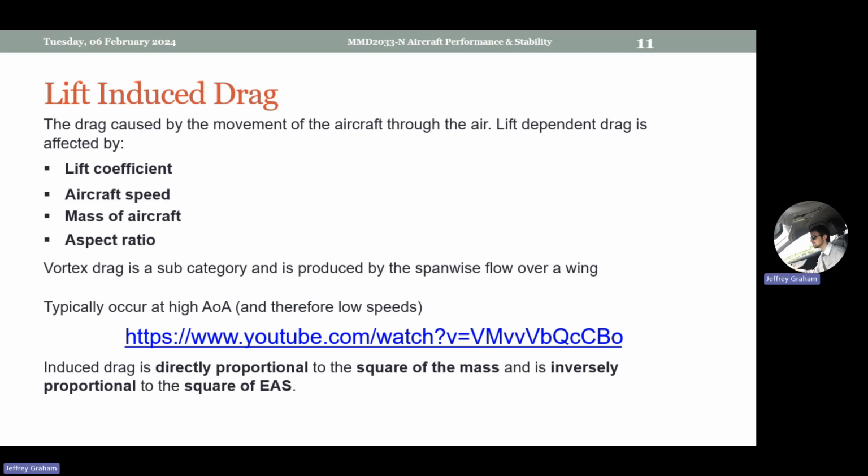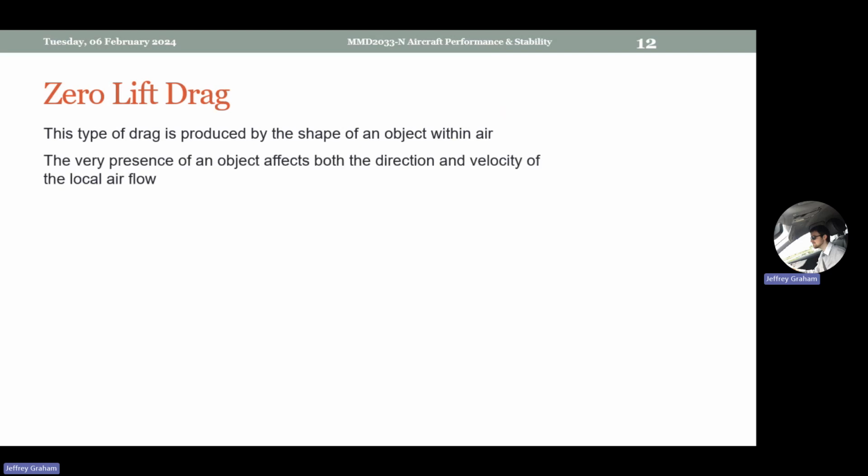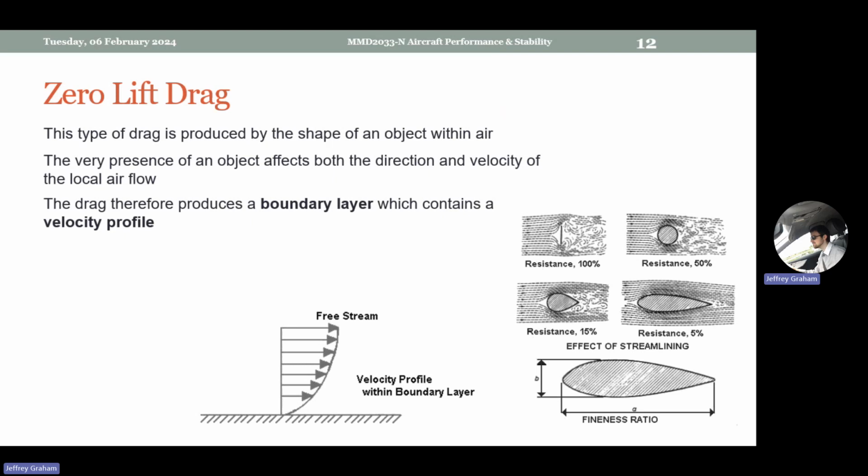As for the other one, unfortunately, it's a bit less glamorous. The zero lift drag, I've already mentioned, is the fact you've got a shape there. So for an aircraft, you have to analyze the individual components. You can get build-up methods often seen in some analysis, come out with an overall value for the zero lift drag for the object you're looking at. So in this case, the aircraft. And you'll see all this is getting at is the shape we've got produces X amount of resistance.